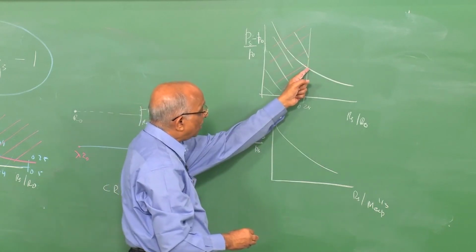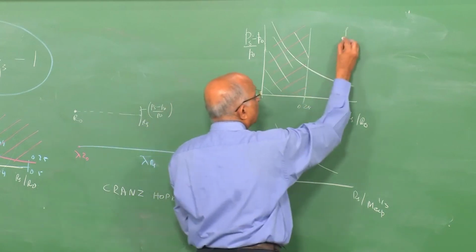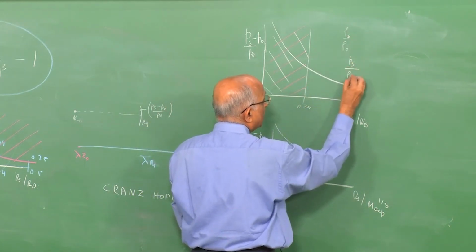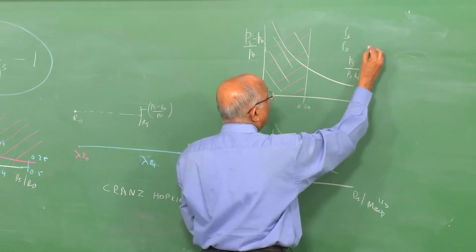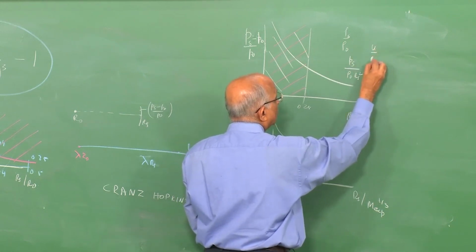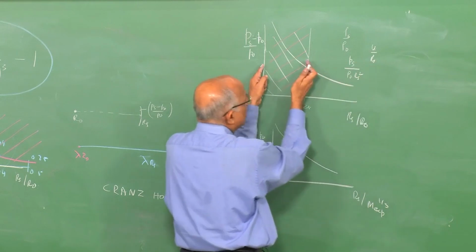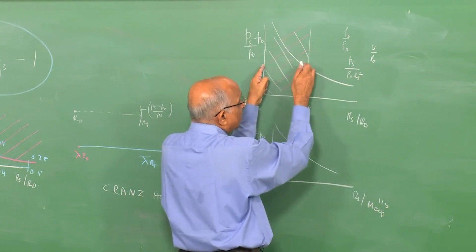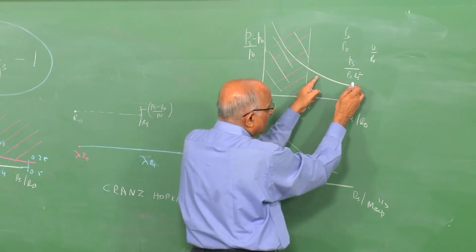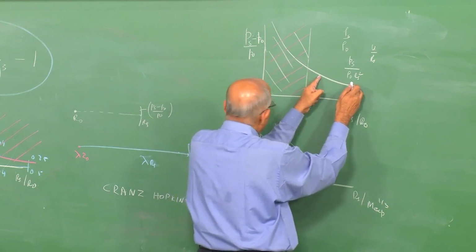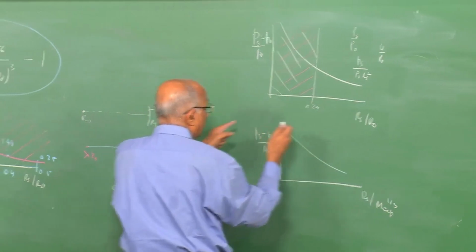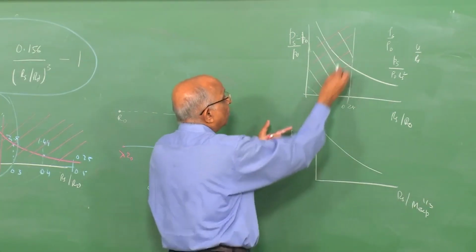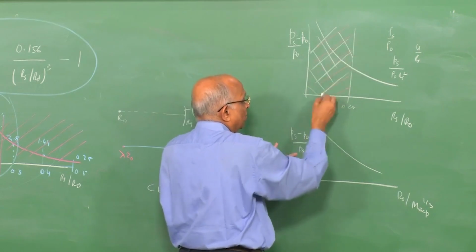Because we showed earlier that the value of rho by rho 0, at the shock front Ps by rho 0 Rs dot square and the value of u divided by Rs dot are all about the same in this particular region, because the jump conditions did not really depend on the Mach number square, whereas in this region it is a function of Mach number square. Therefore, the integral which we used here in the expression as equal to 0.423 may really not be valid, and therefore, it is only in this region which we can use.